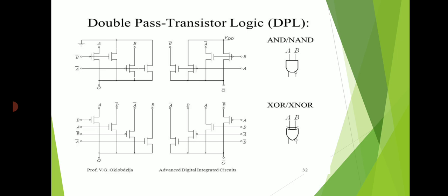And also this has two inputs. Here you can see the two inputs, and also it considers the complements of the inputs. So totally it has four inputs. Here we don't use inverters for complementing the inputs, because if we use inverters, the transistor count will increase the power dissipation and also increase the total inputs present in the gates.